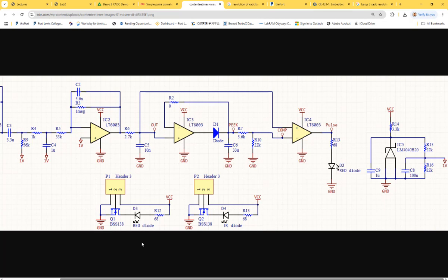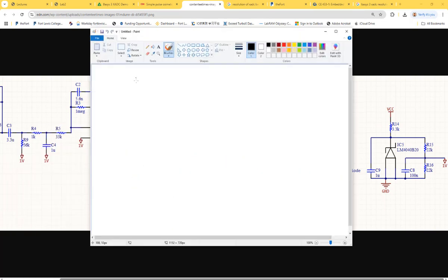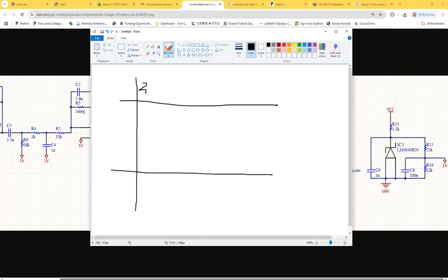So eventually, your amplifier has a range of 3.3 volts over here. However, that DC offset is just at 0.5 volts. So you're expecting your signal to swing around 0.5 like this, just wasting a lot of range over here.